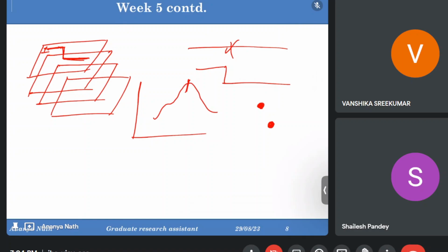And when we went for overaging, or kept the material for a longer time, the precipitates continued growing and formed bigger clusters, bigger precipitates, due to which the distance between them increased, that lambda increased, and due to which the dislocations got a free path to move forward.